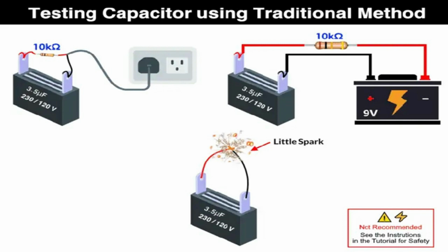Note, keep in mind that a polar capacitor should not be connected to the AC supply. On the other hand, a nonpolar capacitor can be attached to the DC supply because they are back-to-back electrolytic capacitors. As we know, capacitors block DC but let AC pass, but still it will charge with the DC supply source until it reaches the terminal voltage level. In short, nonpolar capacitors can be operated on both AC and DC supplies, while polar capacitors only operate on DC. For more details, check the previous important post on what happens if we connect a polar capacitor the wrong way.